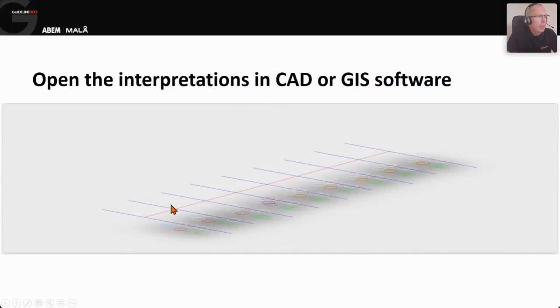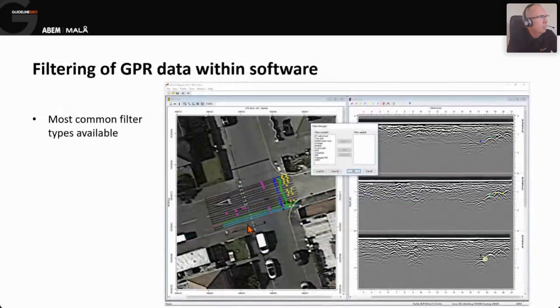So once we export it, the markers will be taken out. We will have two sets of markers taken. So if I just placed one marker into that data set, when I open that up in the software, there will actually be two markers. One of the markers will have a 0 Z value, i.e. on the surface, and then the second marker will have the Z value of what I picked at that marker in the data set itself. So there's two sets of data markers there. But you can see there's a whole series of markers, one above the other. But that then can be opened up, like say in AutoCAD or something similar, or GIS, etc.